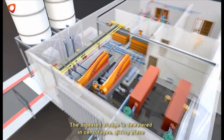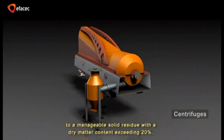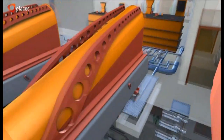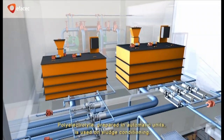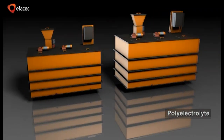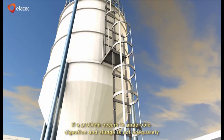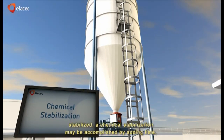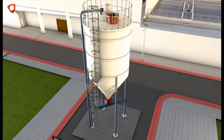The digested sludge is dewatered in centrifuges, giving place to a manageable solid residue with a dry matter content exceeding 20%. Polyelectrolyte, prepared in automatic units, is used in sludge conditioning. If a problem occurs in anaerobic digestion and sludge is not adequately stabilized, a chemical stabilization may be accomplished by adding lime.